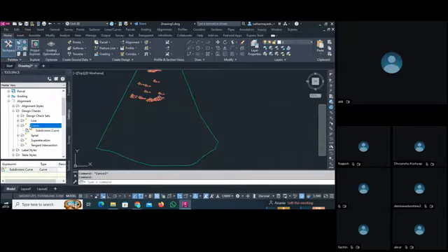And in design check set, if you click on the design check set and create a new one, you can set your new folder. Like I set my 123 folder, and whatever design check set I created here, I can add that. If I create a curve, then I select the curve. And when we create the k value and select okay, the k value shows here, so we can select the k value and add this. If we select okay, our new folder is set here. So this is the first step. But this step is used when we work on a smaller area, and we have to change only small values.